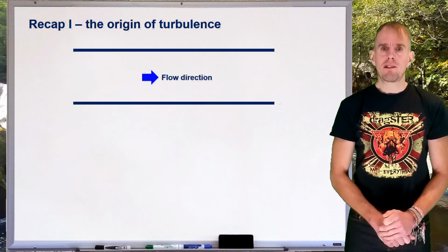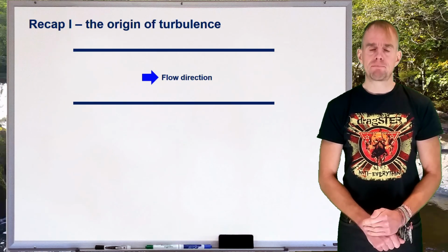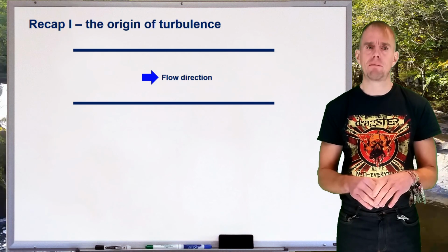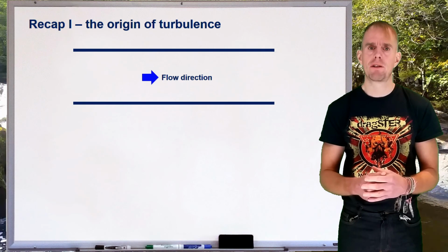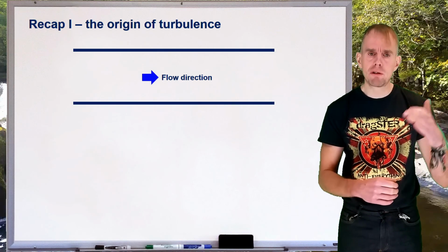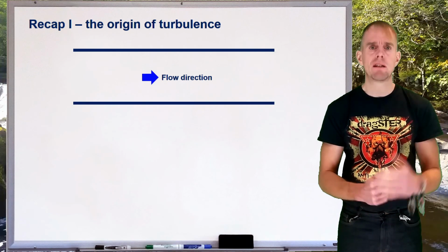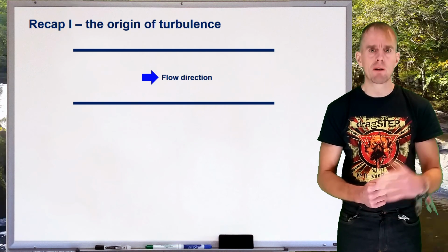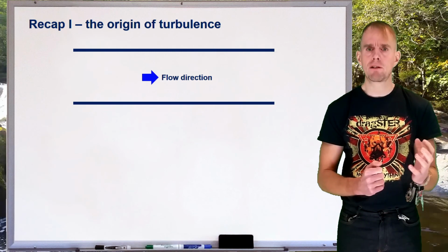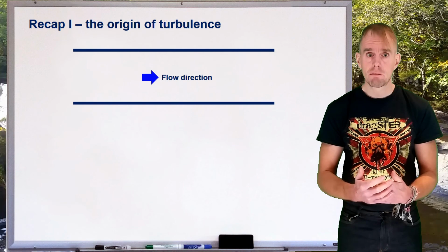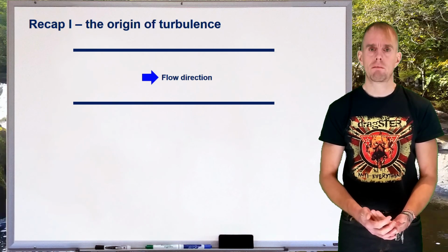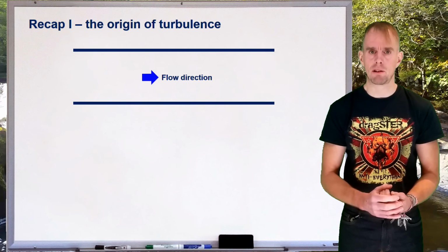Now, let's see why we have turbulent flow. Because when one thinks about it, at a superficial level, it seems rather miraculous that you start with a laminar flow, which is a beautifully well-ordered flow, very easily mathematically described, no chaos, everything perfectly predictable. And yet, if you just make it flow a little bit too quickly, suddenly, it seems, the flow just decomposes into random chaos. And we need to understand why this happens.